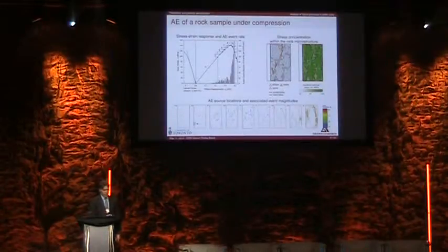We applied this algorithm to a confined compression test on rock. The model, a granite model, was previously calibrated to match the stress-strain response of an actual laboratory test.